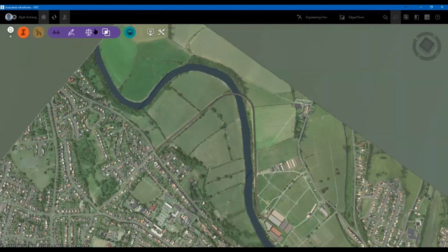If you go into bridge, the same applies where you drop down on the bridge and you'll be able to see further tools available. So you can see, I can design bridges. After designing a bridge, I can review and modify the bridge. Then I can perform analysis on that particular bridge. And the analysis performed on the bridge here are based on the line girder analysis. If I just drop down there, you can see I have two types of bridge I can easily work with.